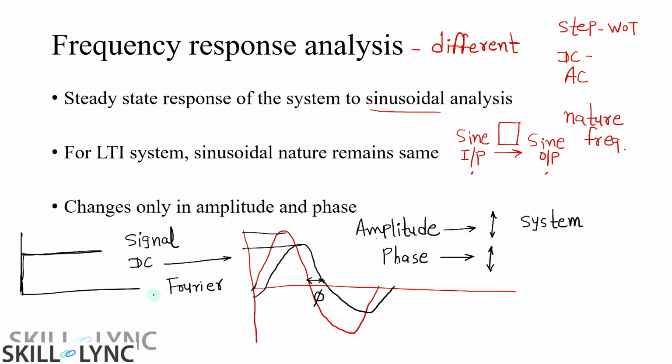Similarly, the same is true in case where we are learning about the inverter which is operated from the battery. We can also build up the sine waves from the DC battery voltages by sine PWM, right? So this analysis, when we consider the sinusoidals, it also includes the DC by default, right? Or when we say that the frequency is set to 0. So if we set this frequency component to 0, then we can call it as a DC analysis.